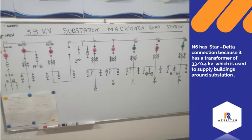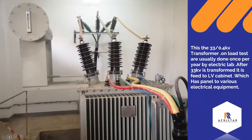So we will go and discuss further what is on N6. On N6, we have a transformer which is connected at this point in star delta connection, and it transforms power from 33 kV to 415 V, and that 415 V is distributed among various equipment, such as the buildings around the station, and equipment like water pumps.